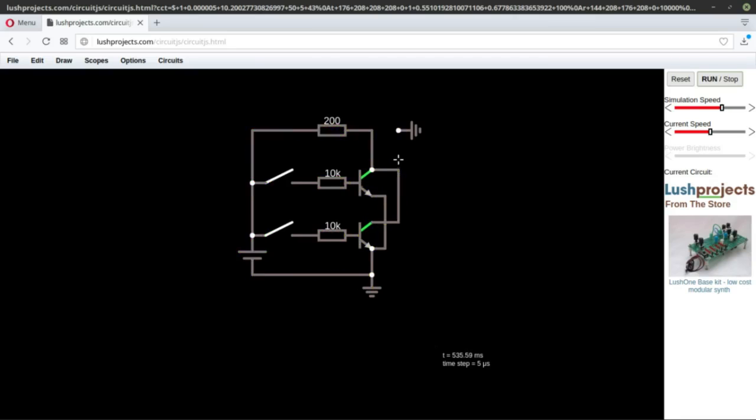Now that previous OR gate that we saw does not really work for all purposes. It does behave like an OR gate, but it is not really a gate, because we have to connect whatever component within this. We cannot transfer this to a different circuit and then get its response back, because this ground is the ground for this input, but it does not really reference this ground. If you didn't understand, just understand that this creates a problem.